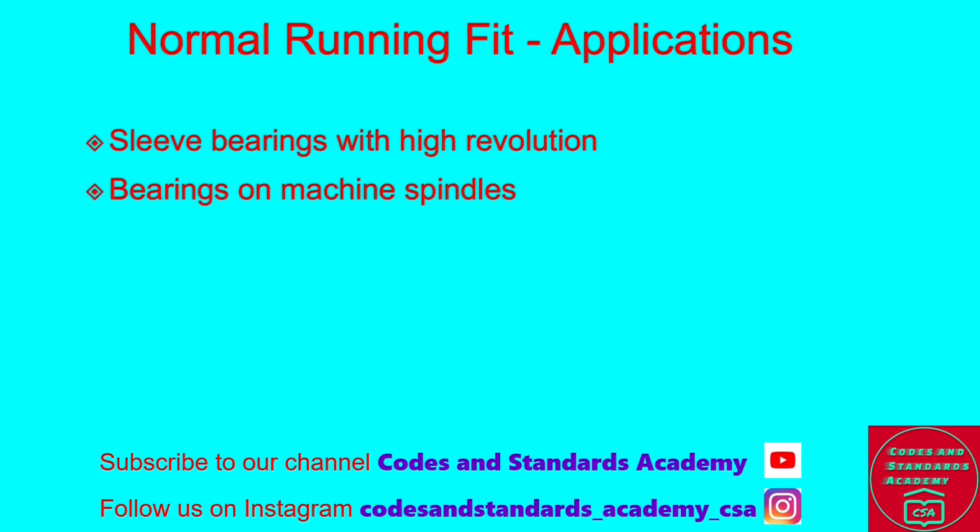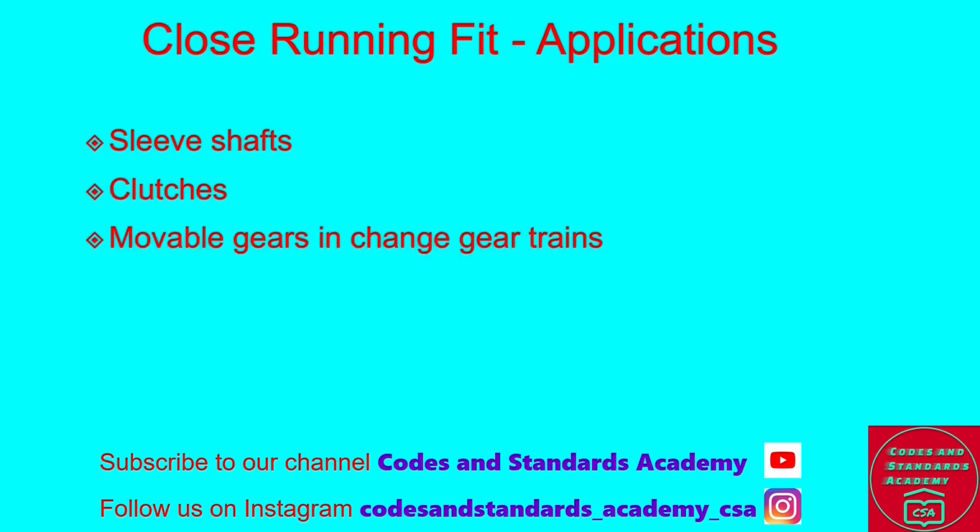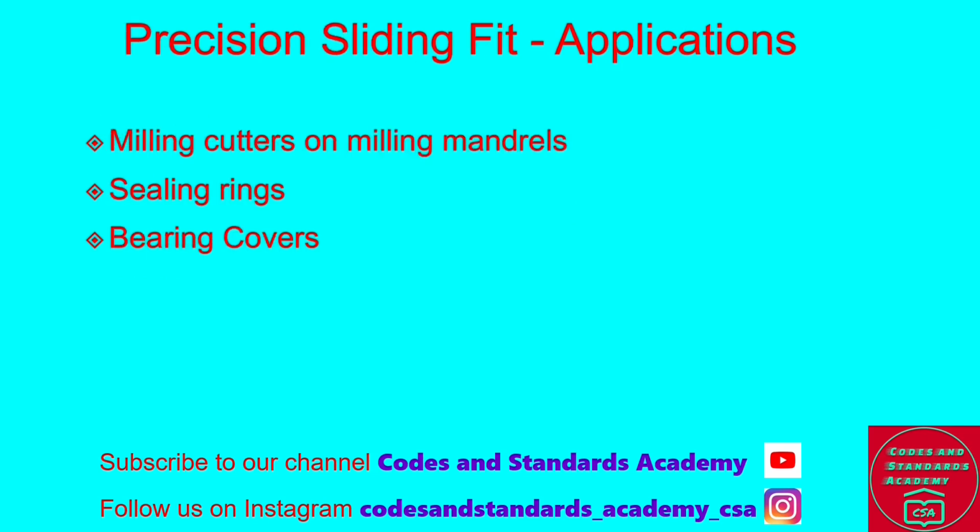Normal running fit applications: sleeve bearings with high revolution, bearings on machine spindles. Close running fit applications: we have sleeve shafts, clutches, movable gears and gear trains. Precision sliding fit. The applications are in milling cutters on milling mandrel, sealing rings and bearing cover.